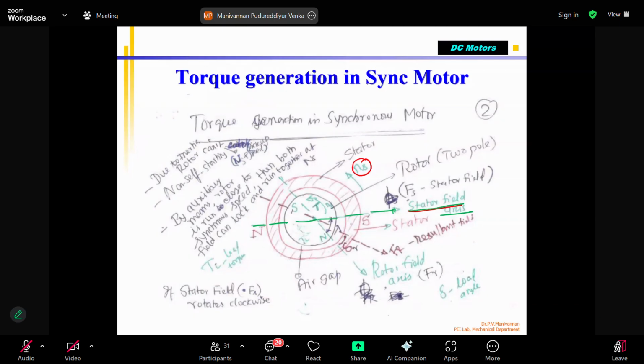Okay. Then at that time instant, the rotor, correct? My rotor magnetic field is this. Again, I'm drawing, you can see that this is the center of the rotor. This black color circle is the rotor, and this is my direction of magnetic field at that instant. Correct? We generally represent magnetic field as a vector. So this is my stator field. This is my rotor field. Correct? The rotor magnetic field is represented by F subscript R. This is F subscript S.